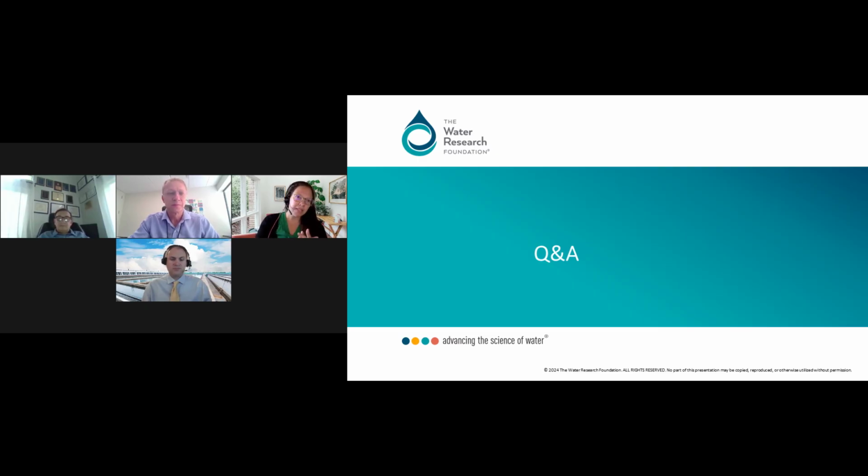So the minimum mixing requirement is something that's typically considered when we're doing our design calcs, when you're trying to decide on the optimal diffuser count that can meet your low to high conditions. Us engineers use a rule of thumb, like 0.12 SCFM per square foot, which is a rough rule of thumb from a textbook value. But we also recognize this can be very site specific, and CFD modeling can be done to help iron out how low you can actually go with that number. There are some papers that show some sites are able to get much lower than that.